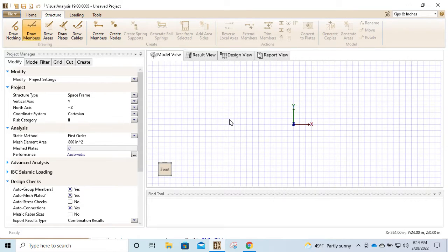These are 1D line elements like we derived in class. Linear axial displacement assumption, that's the field function that's assumed. It's a linear displacement in the axial direction. It's a cubic in the transverse direction. We developed those equations, and that's what it uses. So if we want to draw a member, we could just draw it. We can draw these areas. Areas we've talked about, they're essentially a plate without stiffness. It's just a means of distributing load to members, or plates, things with stiffness.